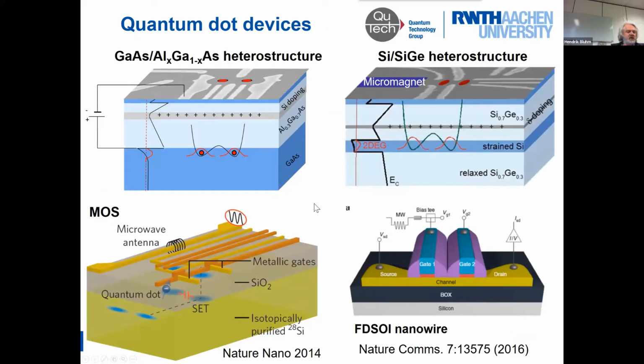So here we go. Let me just elaborate a little bit on the devices that this applies to, and it's basically all kinds of electrostatic quantum dots. The pioneering or legacy devices here would be in gallium arsenide heterostructures. Nowadays, silicon, germanium, or various silicon MOS types are more prominent. And what they all have in common is that one tries to capture individual electrons through a combination of band structure engineering, which then is typically fixed and doesn't need to be tuned. But for lateral confinement, one uses electrostatic gating to define the potentials that capture individual electrons.